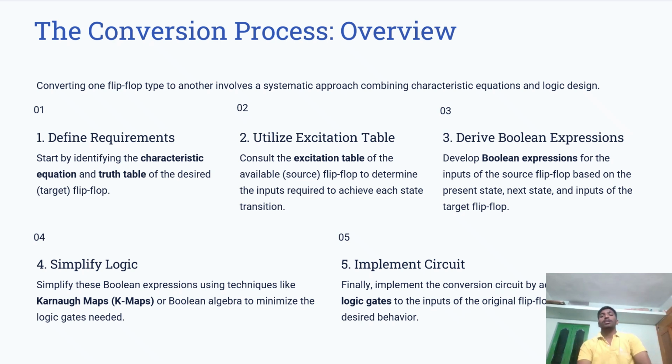Derive the Boolean expression. Develop Boolean expressions for the inputs of the source flip-flop based on the present state, next state, and inputs of the target flip-flop. Simplify logic. Simplify these Boolean expressions using techniques like K-map or Boolean algebra to minimize the logic gates needed.